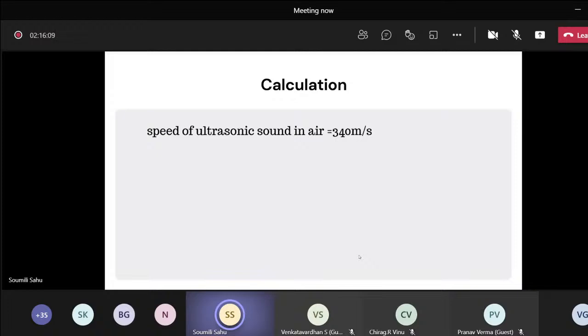And here we are using the time unit microseconds. We are triggering the sensor by keeping the trigger pin high for 10 microseconds. So we need to change the units. Meter should be changed to centimeter and second should be changed to microseconds. How do we do that? 340 meter is equal to how much centimeter? How can we convert meter into centimeter? Divide by 100, or multiply by 100? Multiplied by 100. Yeah, it is multiplying by 100.